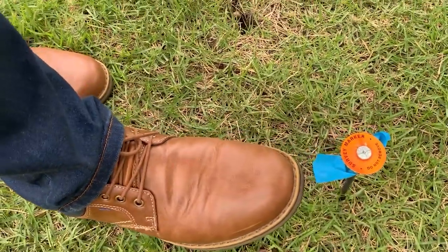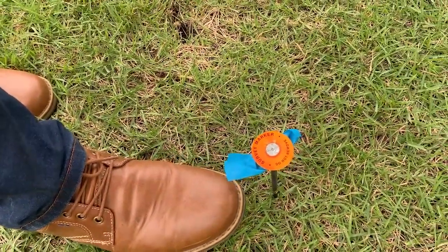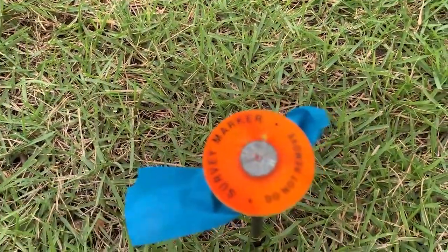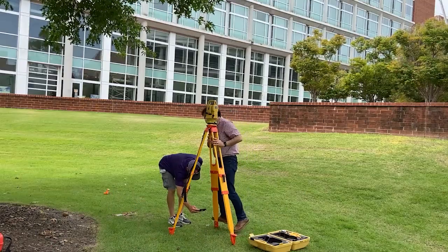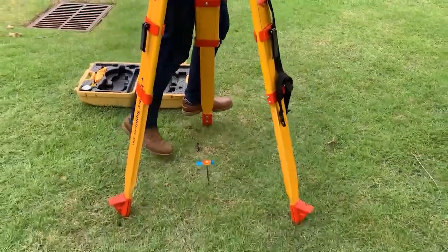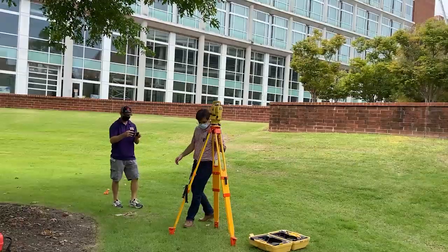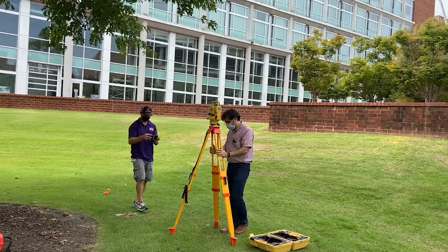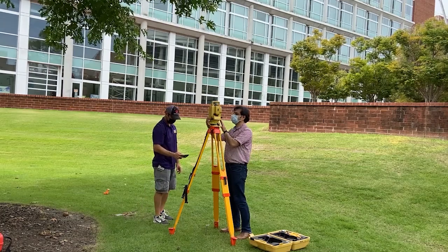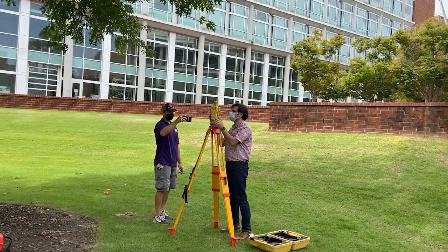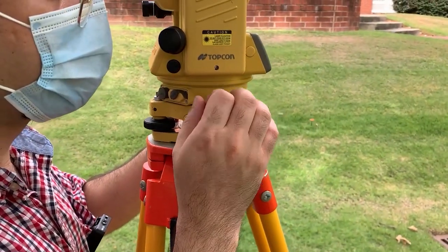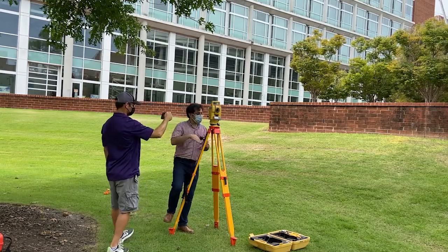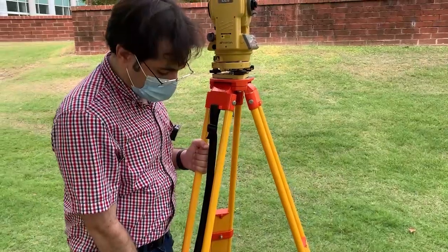Okay, it's right here. And then you move it until you get this laser plummet at the center of the head of the nail. Once you do it, you push these 2 legs hard into the ground. Now still the laser has to be on the nail, but it is not level. It has a bubble level. So the same thing, it would be better to play with the legs first. So it's like this. That means that I need to bring this down.